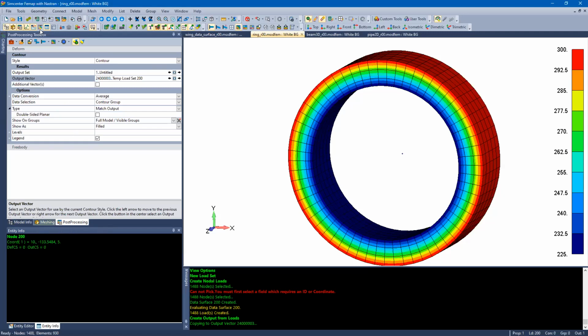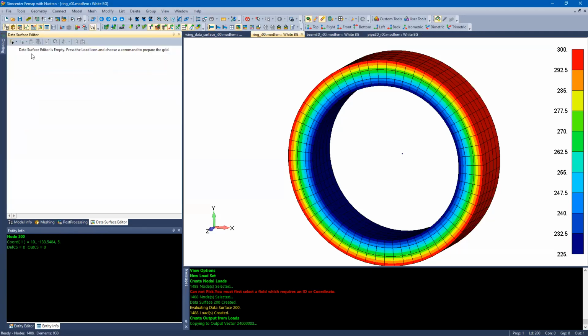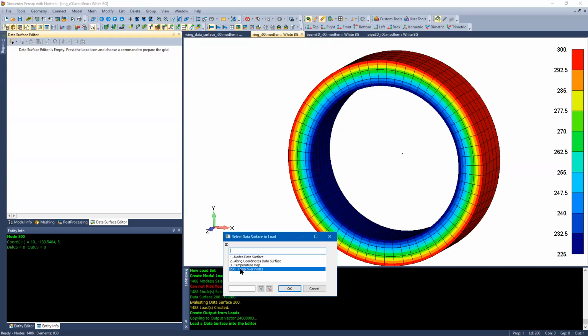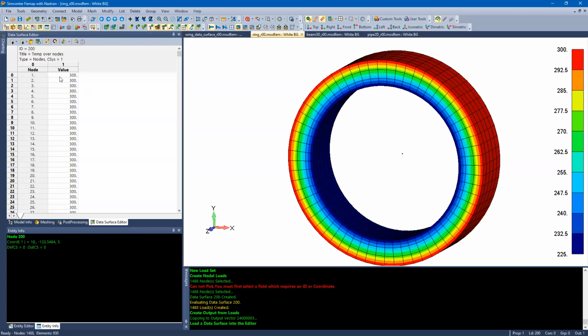And we did not use the data surface editor at all in this case, so we can turn it back on. I used the toolbar to do that, and then instead of creating one, we can do reload/edit. I want to take a quick look at the one we just created. So notice instead of using column 1, 2, 3 to represent each point, it just used a node ID for each of those in this table. And for each node, there's a corresponding point. A node has XYZ or arc theta Z defined for it, so it is a coordinate in 3D space.